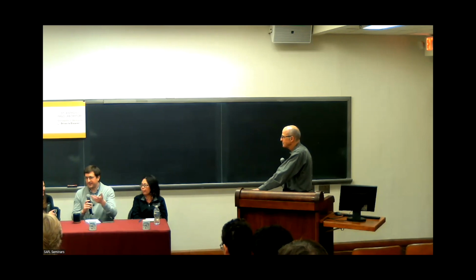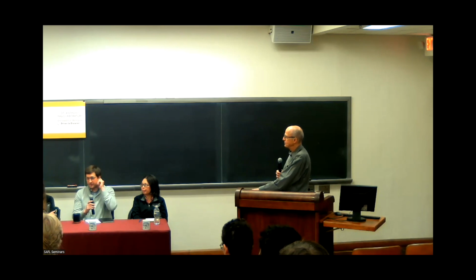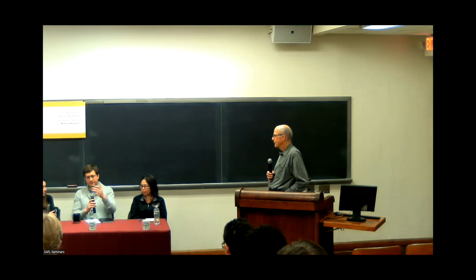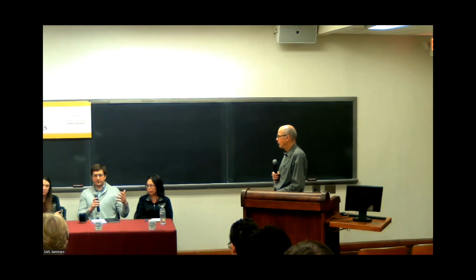All right. To piggyback on that, take small risks with it and try to monitor it. If you can monitor it, that's great. Then you know if it's working or whatever. If you just install it and say, okay, well, it's still drawn down in 48 hours, I'm fine, you know. But if you could start out small, we started out really small with our biochar stuff. We were looking at insert catch basins, and it was a small buildup when we were adding biochar to these because we didn't have a whole lot of data for it. You know, we had some data from the laboratory and whatnot, but yeah, so the small risks, and you'll learn some lessons in those. And we even learned some lessons when we thought we were all systems go on some of our large regional designs.